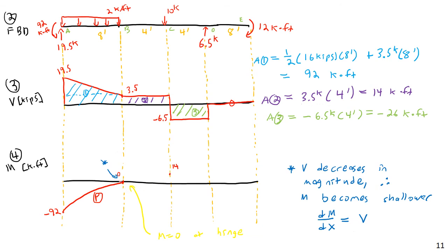Then the question becomes, what kind of function do I have? Well, I know that the integral of a constant value function is a linear function, so that means it's going to be linear from here to here. If I were to draw this exceedingly accurately, I would make sure the slope was the same as we had all the way across. Not to scale. So we're at positive 14, and I'll put an L here to indicate this is linear.